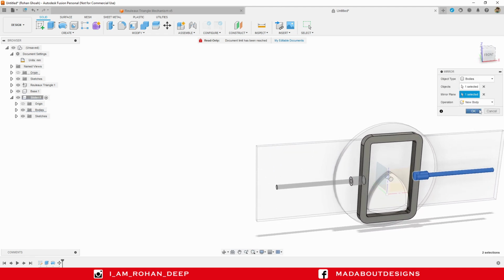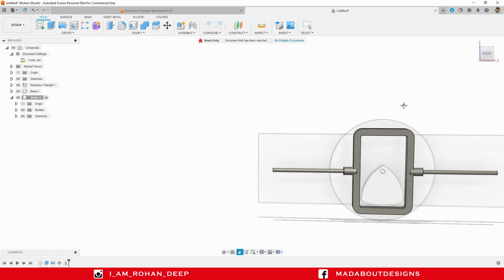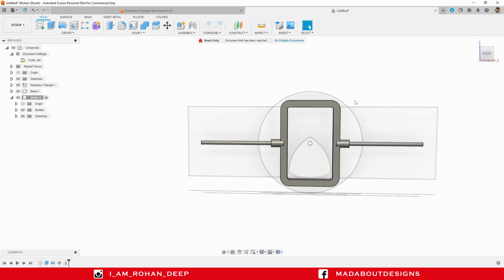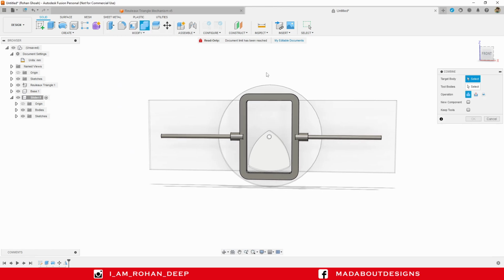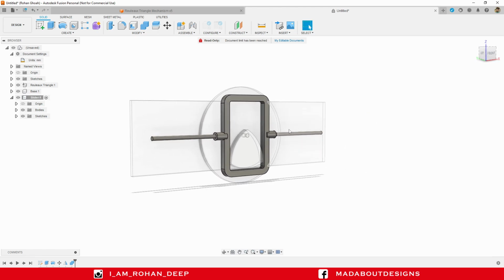Operation new body and click OK. Join all these three bodies. So under modify, go to combine, select all these bodies, operation join, click OK. Here is our slider almost ready.